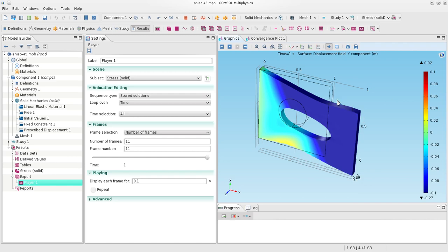So now you can imagine that if the fibers were running not like this, but in the other direction of 45 degrees across the other diagonal, when I pull, it would have moved up. Or conversely, for this example where they run in that direction, instead of pulling, if I pushed, again, it would have moved up, right? So the orientation is very important. And that's why we said that the orientation of orthotropy of the fibers is very important.